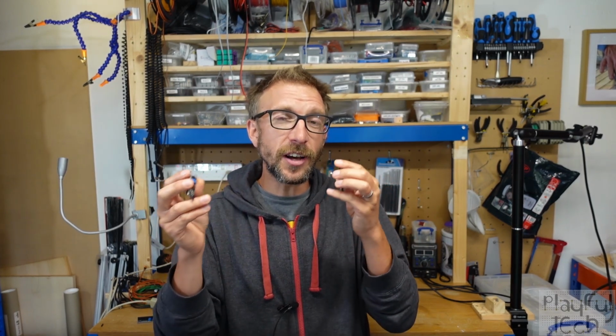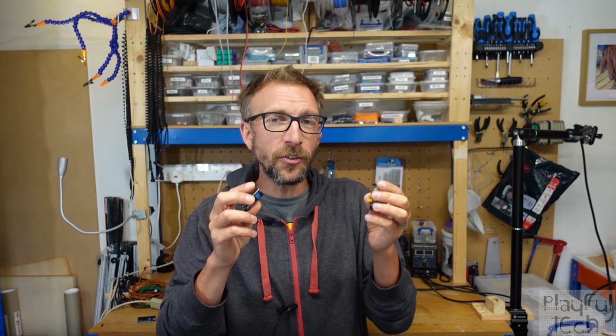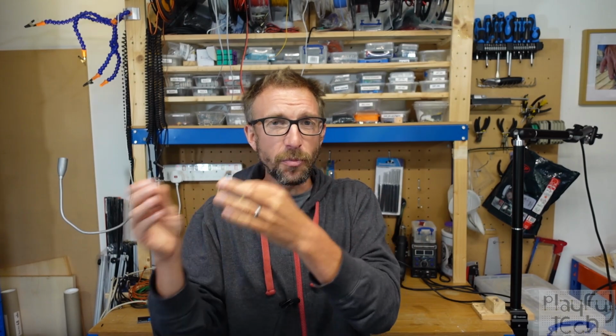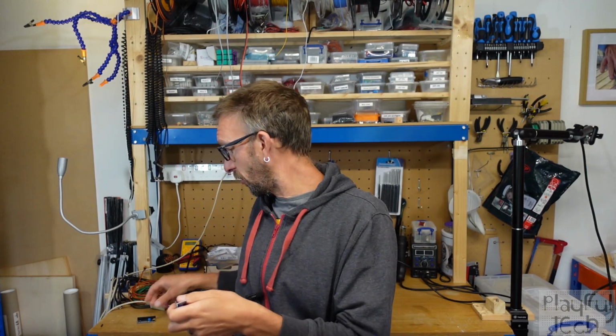Also, they're not quite as fast as built-in GPIO pins because there's that extra layer of abstraction from the microcontroller. The I2C interface that they use carries the signal from the processor to the chip, typically at a clock speed of 400 kilohertz. So that is still way fast enough to deal with anything involving human input, like a button or a switch, but it might be a factor to consider if you're dealing with sending data between very fast devices.